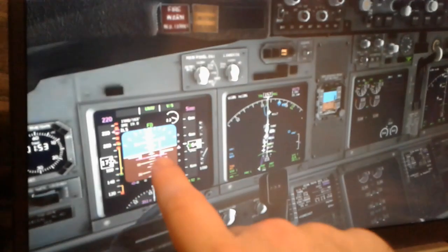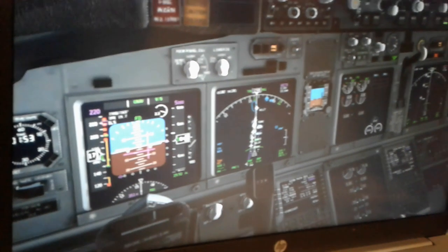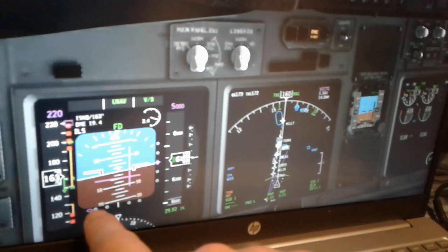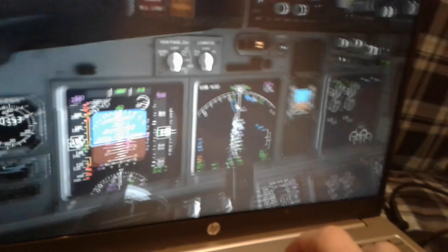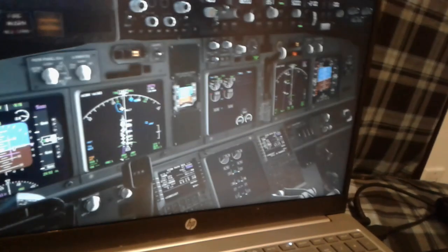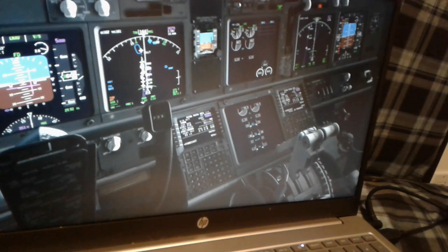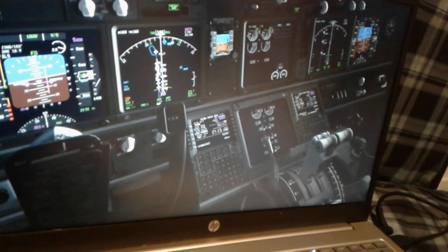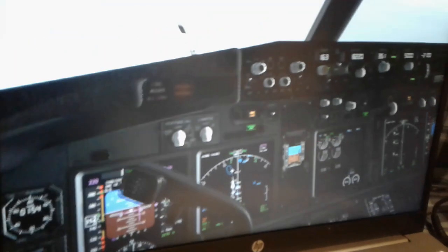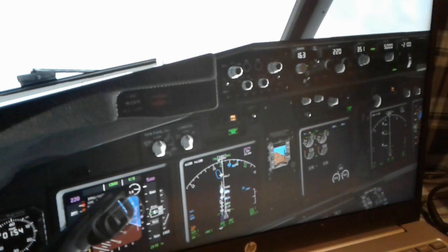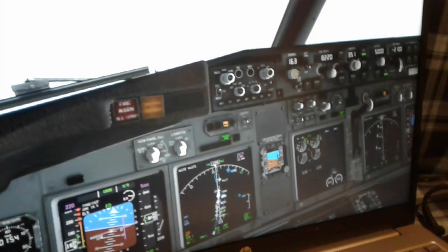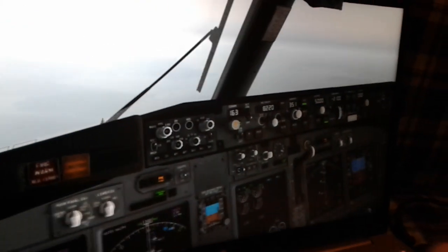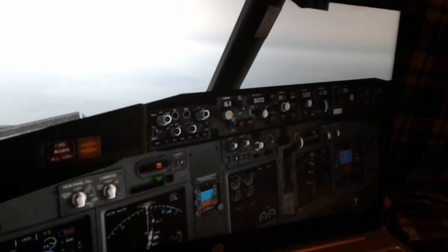So we are in the ILS localizer over here as we are approaching the correct glide slope, and now the ILS localizer is a little bit to the left. We're going to be approaching. We need to add some thrust again. Speed brakes now retracted. Gonna make a bank angle to the left. That's good. We're gonna have a landing gear also down. Landing gear down now.